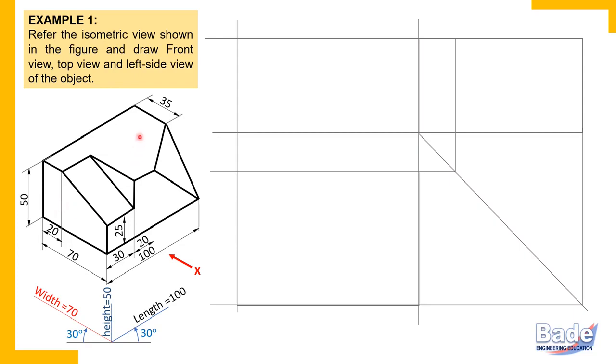Now listen, if a surface is parallel to HP, you may use a thin book, keep it parallel to the ground, parallel to the floor, and check. In the top view, it gives its true shape, but in the other two views, it appears as a line. So the surface which shows a true shape in one view, in the other two views, it appears simply as a line.